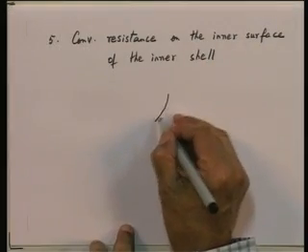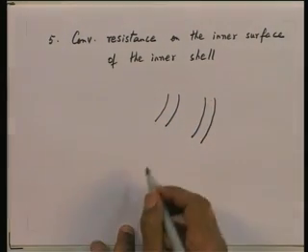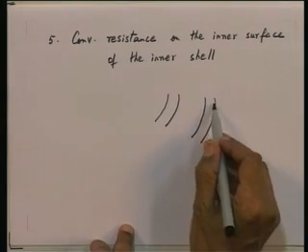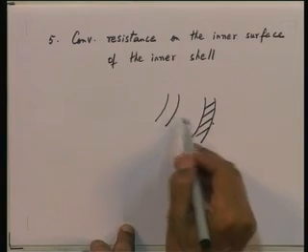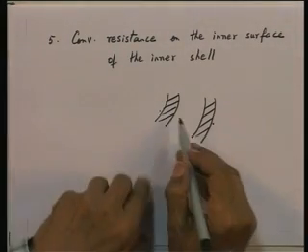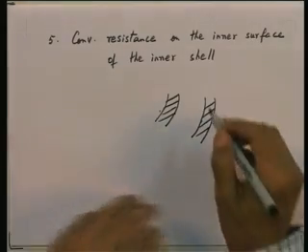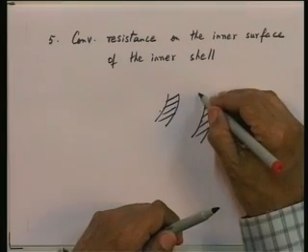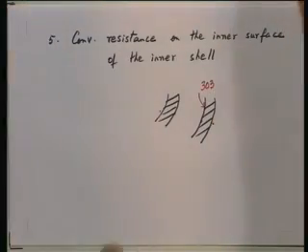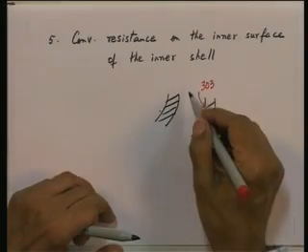So, although I have a situation like this, across the annular space, starting from the outside, a resistance here, a resistance by conduction here, then the radiant heat flow dominant resistance, then a resistance by conduction here, then a convective resistance. I say the dominant resistance is in this vacuum, and therefore, I can take this temperature to be 303 and this other temperature at the inner surface to be 77 Kelvin.